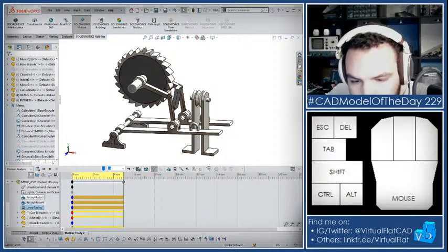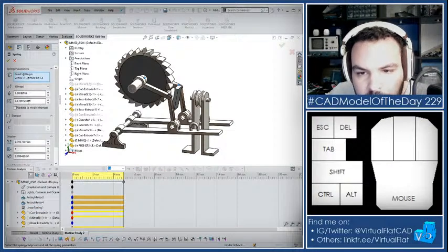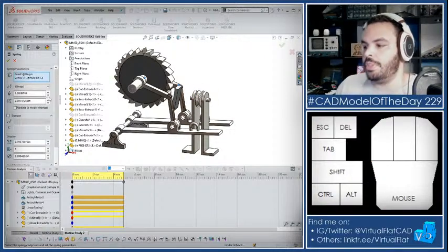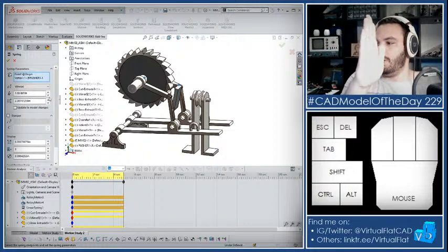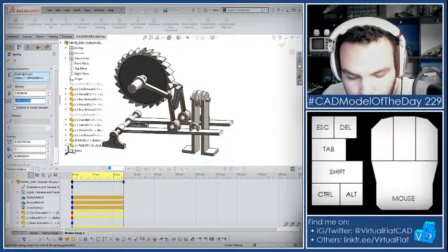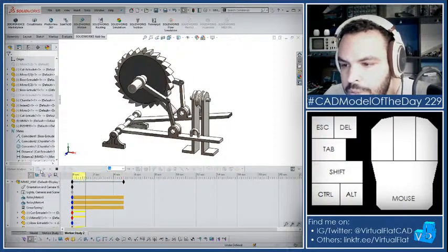Oh, hang on. I need to tell it its length. What is this? The free length? Yeah, just make that really small because I want that spring to pull. Because it's basically doing this: you have a spring, you push on it, it just goes back. But if I make it small, like 1 inch, it'll assume that it's stretched.